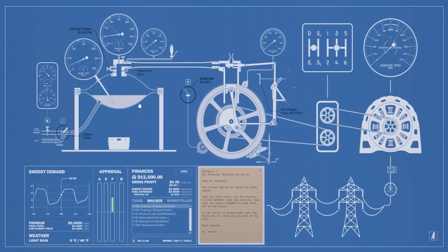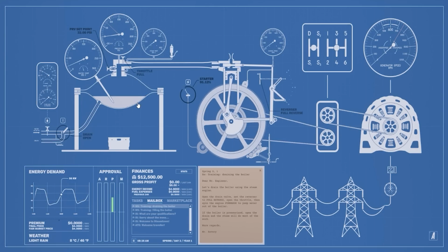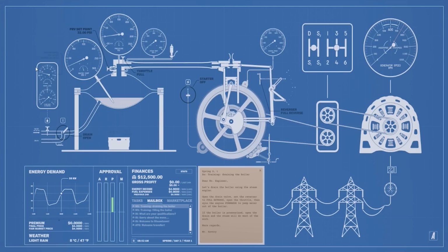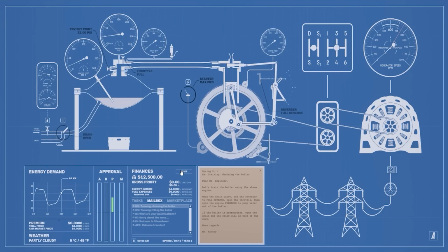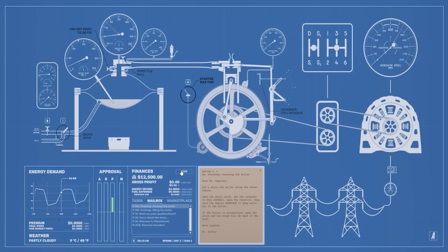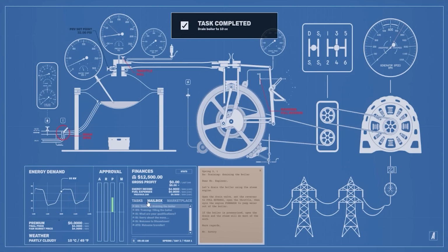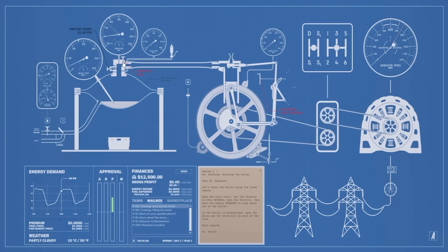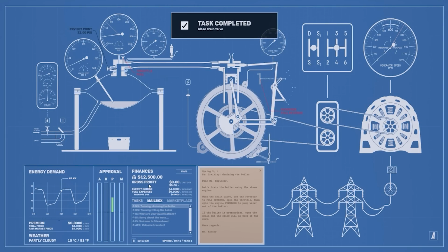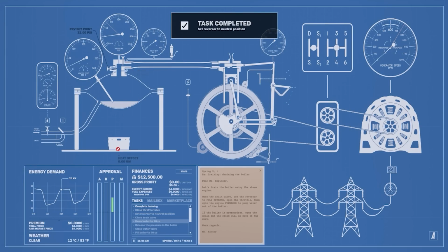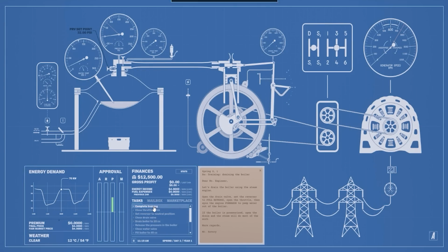Oh yeah, and I guess it's forcing air through the pipework back into the boiler. Yeah, that's going down. We need to get it to 10 cc. 16. And we're using the electric start to do that. And there we go. And then we'll shut the drain. Throttle. What's it asking us to do now? Set the reverser to the neutral position. Neutral. Then close that.